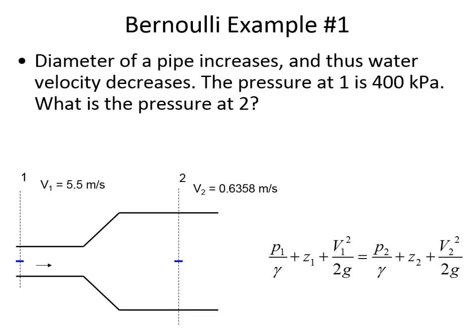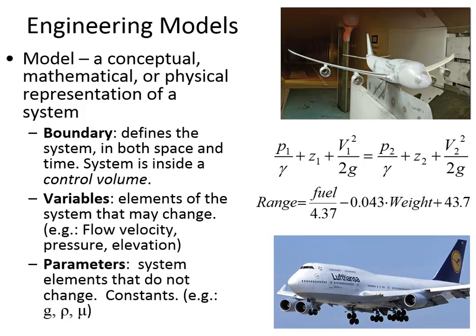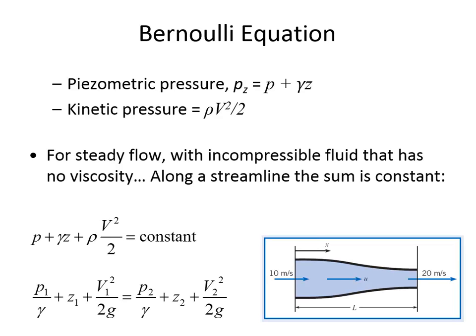And the real conditions is when there are energy losses due to pipe friction. Yeah, there are some pretty complicated empirical equations. Remember, we were talking about the difference between an empirical equation and a fundamental equation. We have fundamental equations that can predict how the pressure changes as a function of a velocity changing, but pipe friction is pretty ugly. We'll get into it pretty heavily next semester in hydraulic engineering, but we have to sort of bend over backwards sometimes to accurately predict what pipe friction is doing.